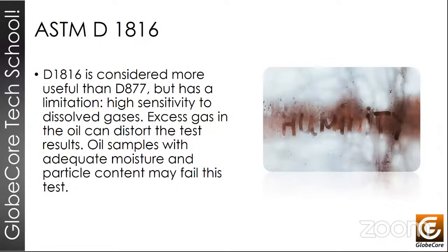Okay, let's look at another method, the ASTM D1816. The 1816 standard, although generally accepted as a bit more useful probably than the D877, has an important limitation. When testing oils in service, this method is very sensitive to dissolved gases. So if we have excessive amounts of gases in the oil, they can decrease the test results significantly, to the point that an oil sample might be generally adequate and acceptable with low moisture and low particle count, but it can still fail the test, which is also a false result. That must be taken into account.